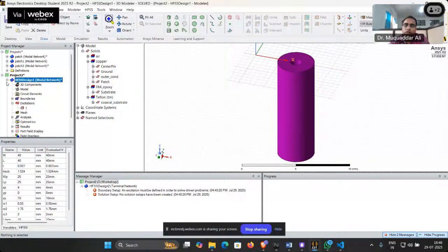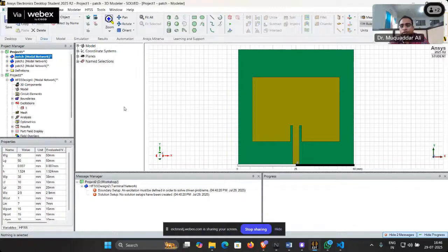So when the antenna terminal is matched with the 50 ohm, then the length of the transmission line from your device to test device does not affect the results much. Okay, so let me show you this one. Here I have created another antenna, and it is also a simple microstrip patch antenna. Now let us explore this antenna.